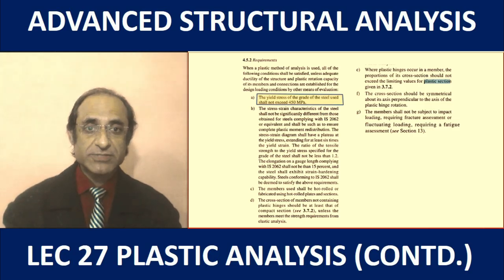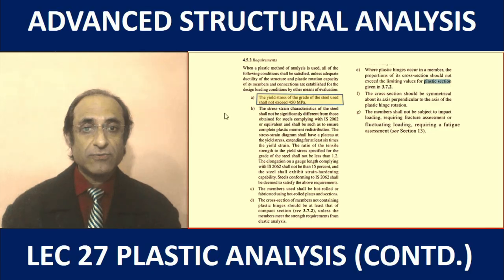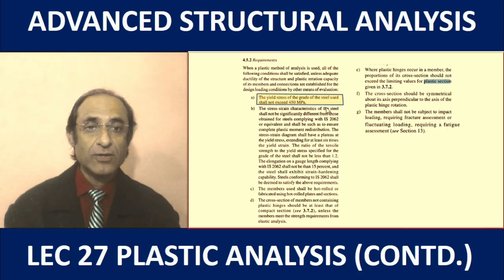There is a limit over here because high strength steel lacks ductility, it's slightly brittle in nature. So that's why the yield stress is limited to 450 megapascal.